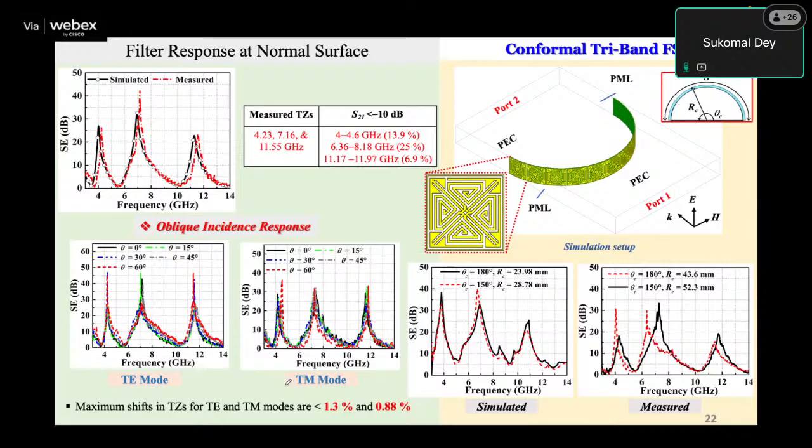Shielding effectiveness is important when you are considering the FSS as a spatial filter. The shielding effectiveness formulas change if you are considering the FSS as a transmissive FSS or as a reflecting FSS. If you are using a transmissive FSS, whether it is a band pass FSS or band stop FSS, the formulas will change.